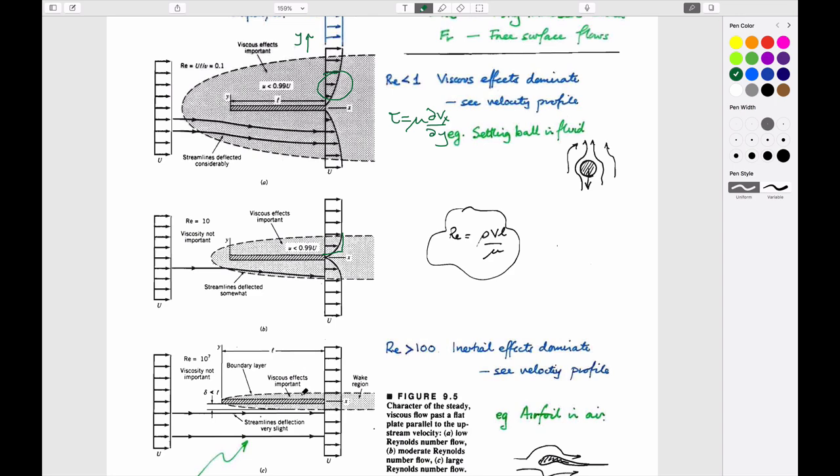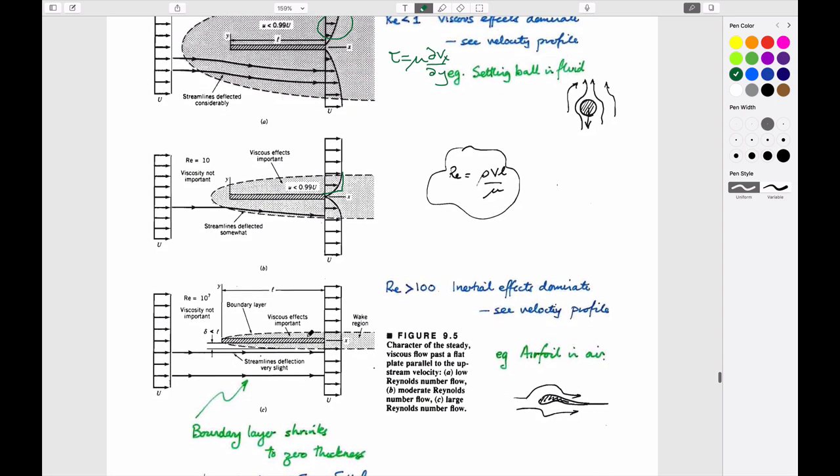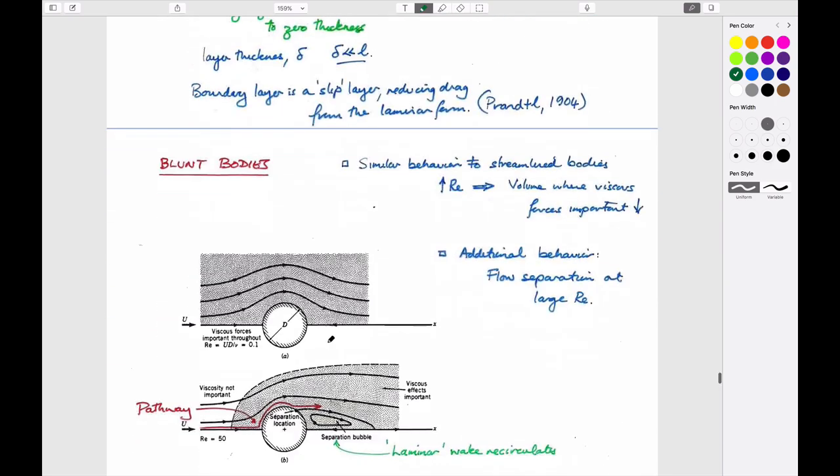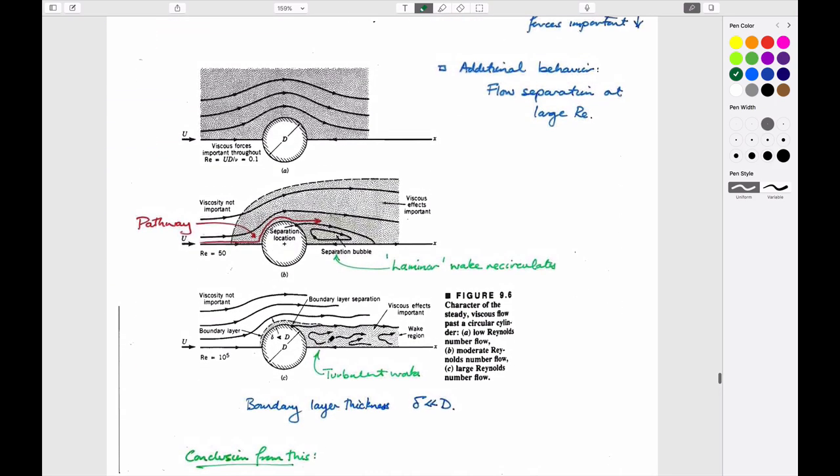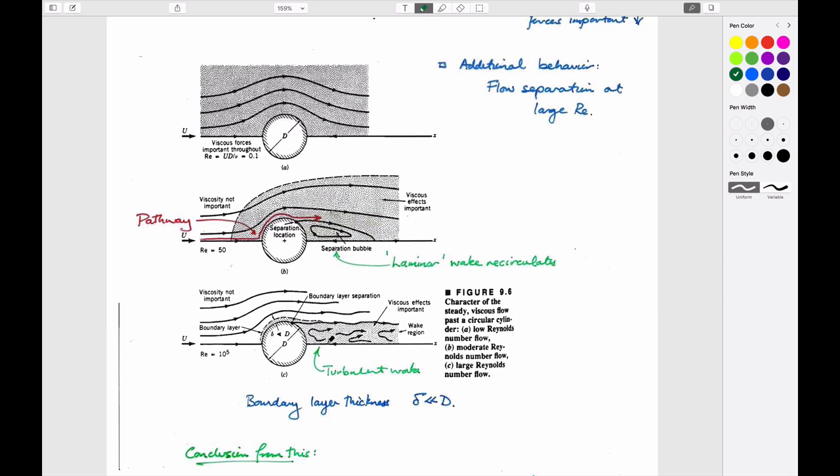And so when you get a boundary layer forming, the boundary layer tends to be a very efficient way of being able to move this through the air. And you see these behaviors not just for a plate, as we saw here, but we've seen it for an airfoil in the example we did. You see it also in the case of a cylinder or a sphere going through the air. A sphere, of course, would be a ball, a golf ball or a baseball, where you get this separation on the backside, and it develops a fully turbulent flow and a wake on the backside here.